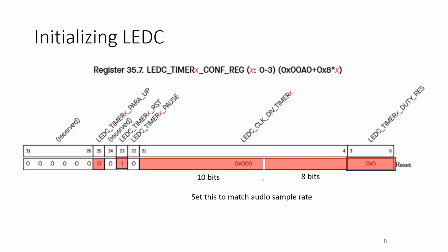So let's go to the LEDC. Okay, so the LEDC is a little bit more complex. A few more registers on this one. The reason for this is that the LEDC is comprised of really two peripherals. There's a timer and there's the LEDC. The timer is what basically counts, right? It takes care of the clock dividing, and it's like the wall clock, right? The LEDC peripheral itself is used to look at that clock and then figure out how to set both the period and the duty cycle.